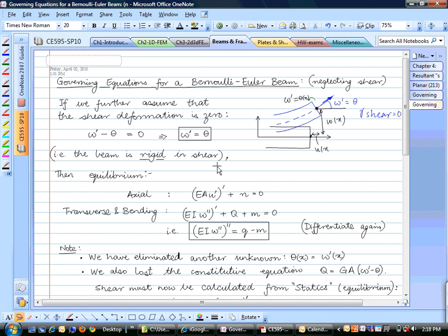On the other end, if I try to do the same bending, then it takes a lot more effort and it's not even bending much. So this configuration is a stocky beam. In this configuration, if you apply forces, there might be shear at every cross section. That is very important. In this configuration, you can neglect shear and all the deformation is pretty much due to bending. Okay.